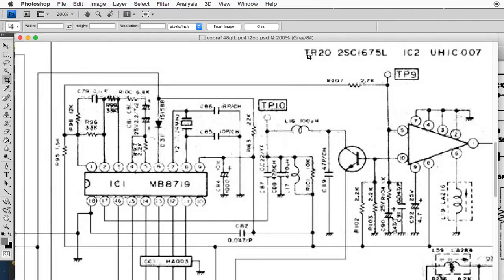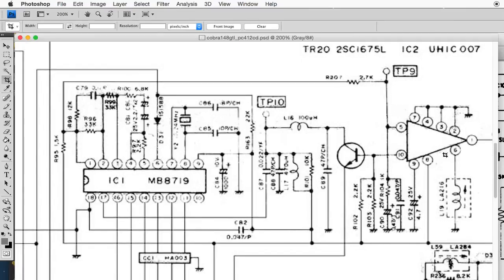Depends on how all this lot's working, but that's no good for generating a frequency here. That has to be smoothed out, otherwise you get oscillation within the VCO as well, like a secondary oscillation. So you'll get like a warble on SSB, for example. The frequency is always changing, or you can hear noise in receive and transmit, where the frequency is always chirping around. That's the effect you can get from poor regulation in here or in here, mostly from this part. So if you do get that kind of thing, it's worth looking at this part of the circuit, because that's likely where the fault lies.